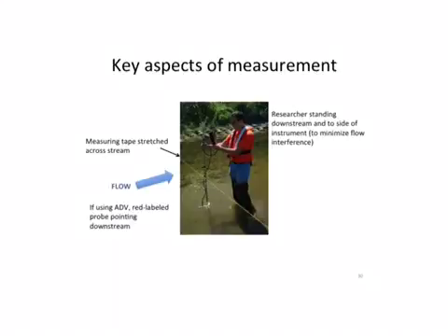Now there are some rules of thumb when making these discharge measurements. One is that you don't want to disturb the flow by your own presence in the stream, and so you want to stand downstream of the instrument and a little bit off to the side. In this particular case, flow is going from this end of the picture to this end of the picture. The other thing is that you'll see that the ADV that we're using has a red probe, and that should be pointing downstream. And again, we'll go over that in Creek.